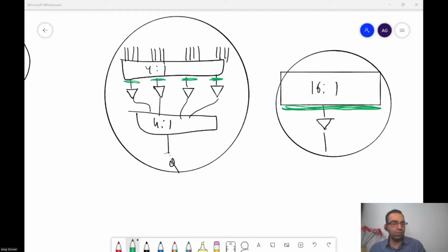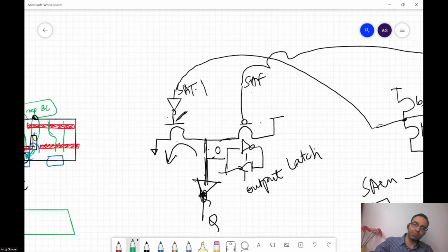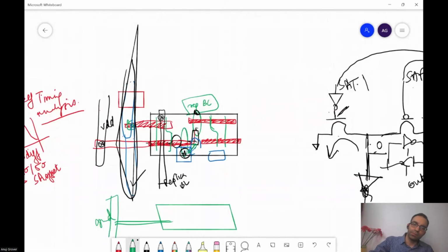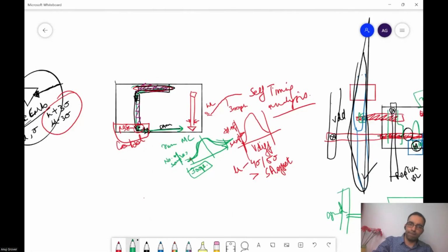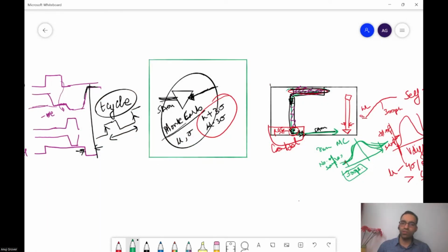Yes, for the first part of your project, that is sufficient so that you get the offset. We measured the offset as the minimum difference between bitline and bitline bar for which the output was pulled to either VDD or ground. Yes, so for this part, this is what you are doing. Just run the sense amplifier model and find the offset.